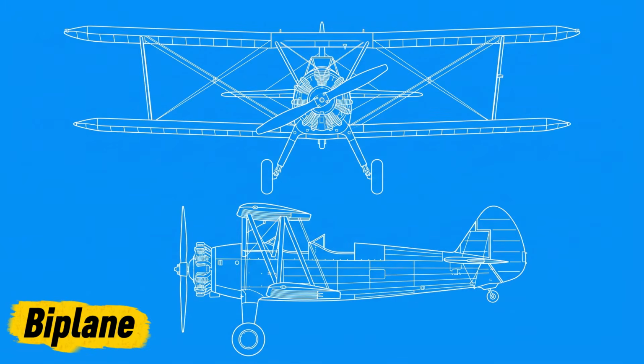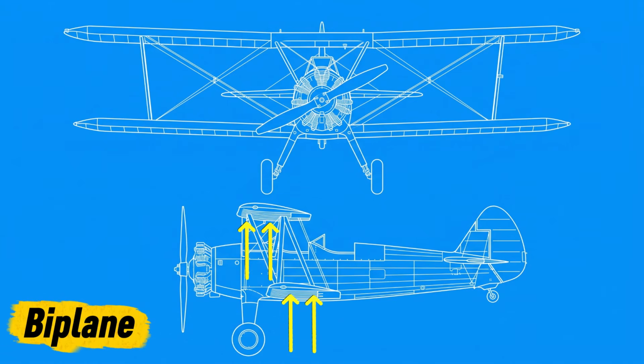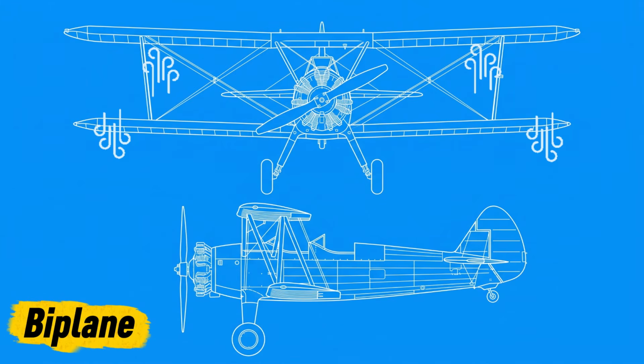The biplane is an aircraft with two main wings stacked vertically, allowing a large lifting area within a compact span. This gives it good low-speed lift and strong structural support, but the close wings interfere with each other aerodynamically, creating extra drag and limiting its efficiency at higher speeds, and it suits low-speed aircraft.